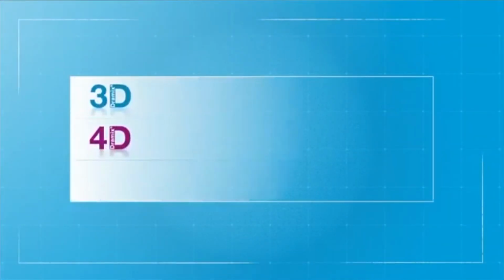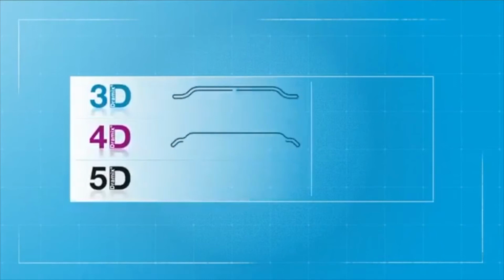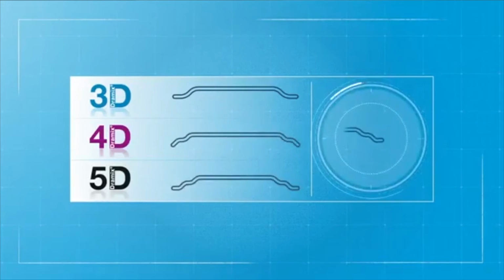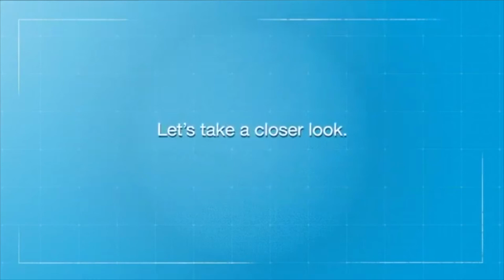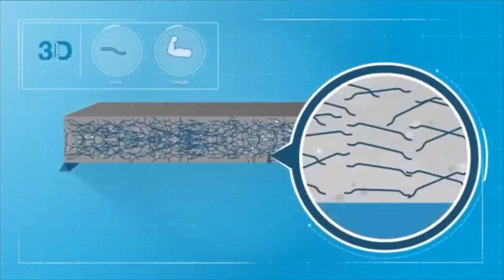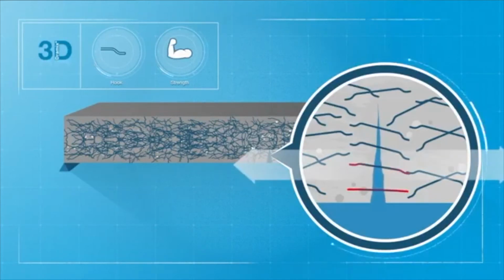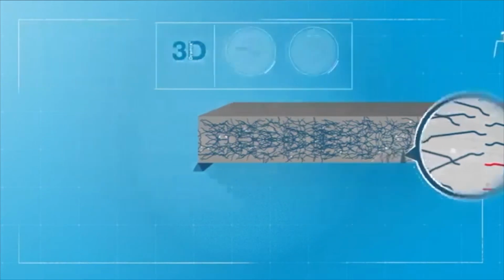Different loads require different steel fibers. To meet any design requirement, Bekaert offers three steel fiber types: Dramix 3D, 4D, and 5D. Each fiber has a different hook, strength, and ductility. Consequently, they also behave slightly differently when dealing with stresses. Let's take a closer look. First up is Dramix 3D. When a small crack occurs, the 3D hooks firmly anchor inside the concrete matrix. As the stress increases, the hook slowly deforms. As soon as the fiber loses its bond with the concrete, the pull-out takes full effect.